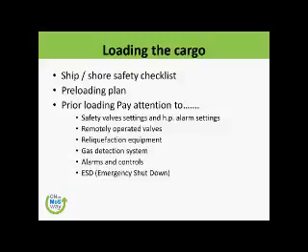There are two types of emergency shutdowns. One is the hot ESD once we come alongside. And once our lines and arms are cooled, we do the cold ESD test before getting the liquid into the tank, and that is what we are going to do in the exercises today.